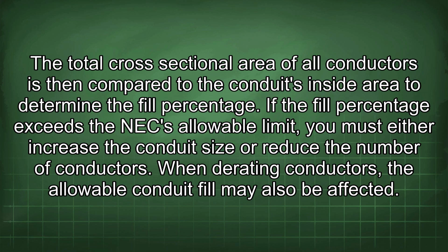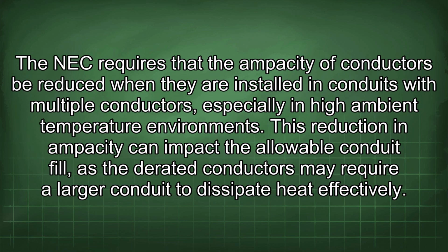When derating conductors, the allowable conduit fill may also be affected. The NEC requires that the ampacity of conductors be reduced when they are installed in conduits with multiple conductors, especially in high ambient temperature environments. This reduction in ampacity can impact the allowable conduit fill, as the derated conductors may require a larger conduit to dissipate heat effectively.